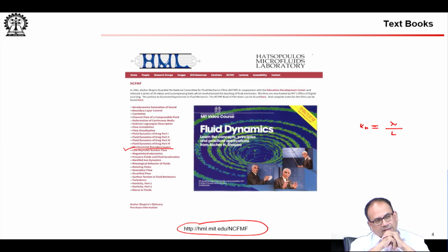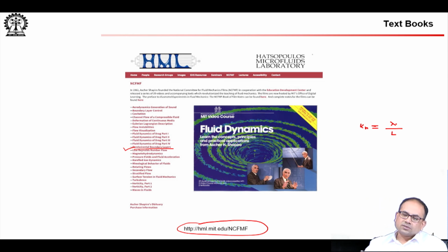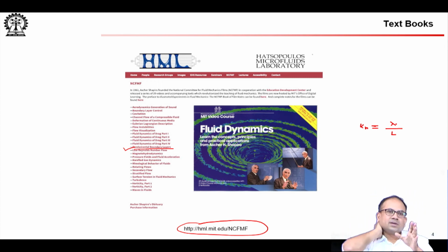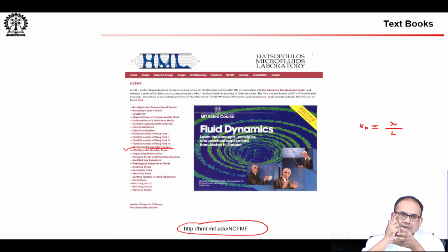As I said in the last class, that powered flight. If you have an air breathing engine, because you need a certain kind of density of the ambient air to even generate thrust, you cannot really go that high where you are having Knudsen number falling in this range where you have slip conditions.